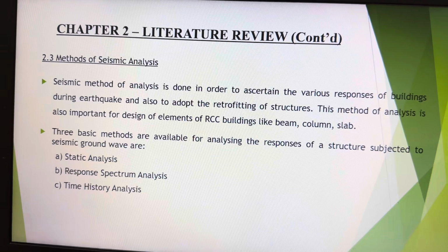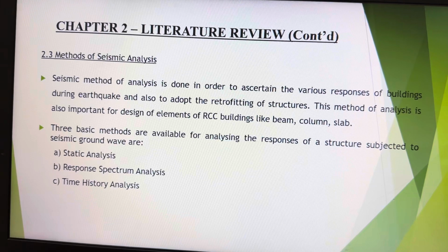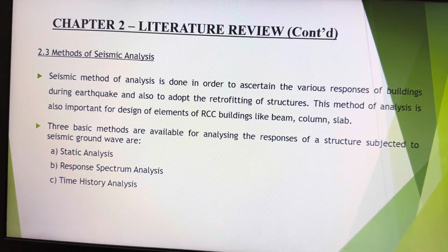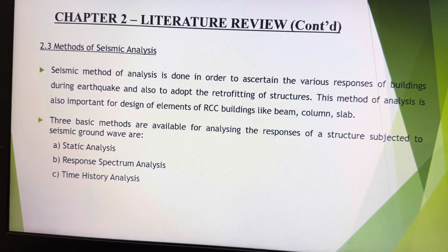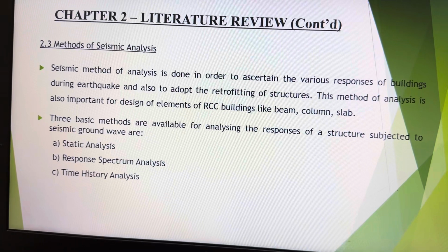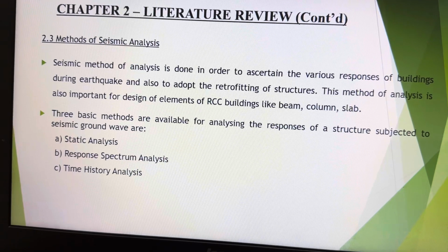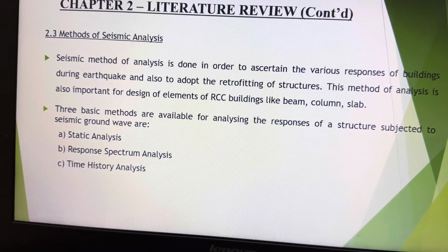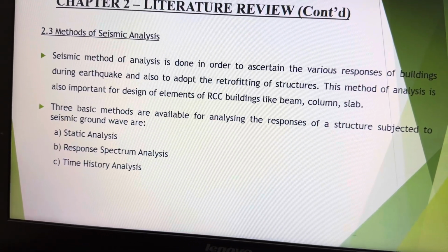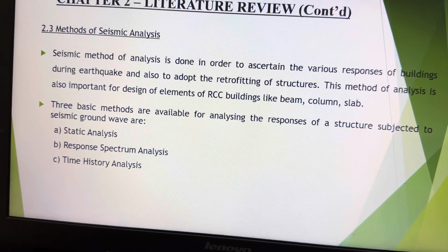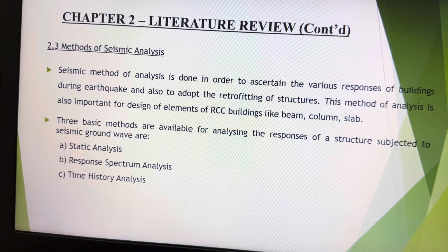In this study also, we will elaborate in detail regarding method of seismic analysis. Seismic method of analysis is done in order to ascertain the various responses of buildings during earthquake and also to adopt the retrofitting of structure. This method of analysis is also important for design of elements of RCC building like beam, column and slab. Three basic methods are available for analyzing the response of a structure subject to seismic ground wave: static analysis, response spectrum analysis and time history analysis.